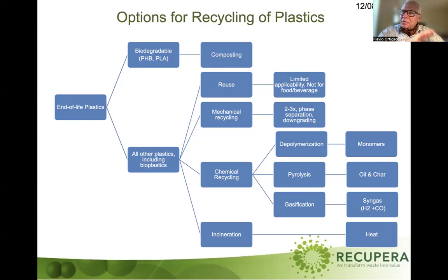And this is good. There's nothing to discuss about that. It's a very clean way to produce new bottles out of old bottles. But it requires that the plastics are homogeneous. It requires that the bottles are very clean. And if you have a mixture, mixed plastics, you cannot use that. This will not work, for different reasons. Then, if you cannot do depolymerization, what about chemical recycling?